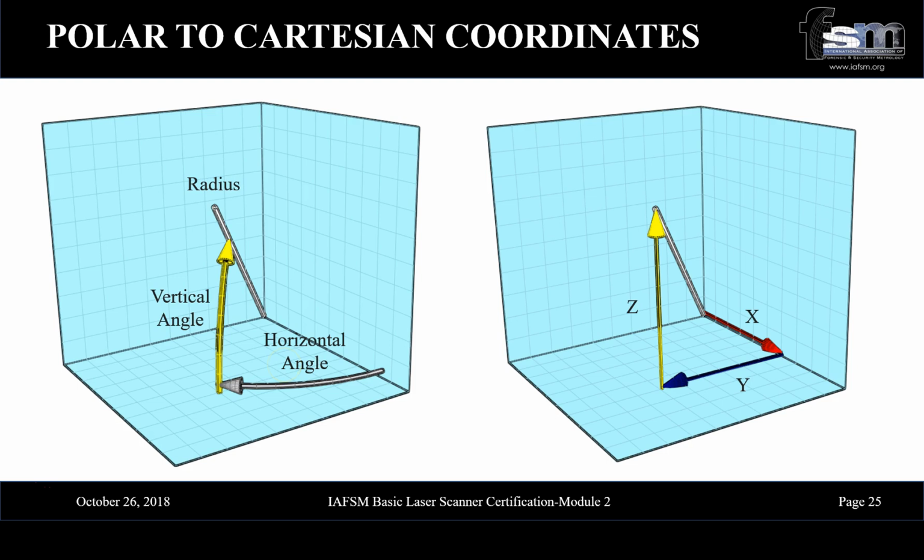Okay, 2 things to understand is that just like a total station, a laser scanner also collects data in a polar coordinate system. And so if we consider that the mirror was right at the 0, 0, 0 point of a coordinate system, we are calculating the distance, which can be seen like the radius of a circle. And we have the angle from the mirror, so that gives us a vertical angle, and then we have the horizontal angle. Okay, so that gives us an angle away from some reference horizontal axis. So by knowing these 3 particular components, we can define a point in space.